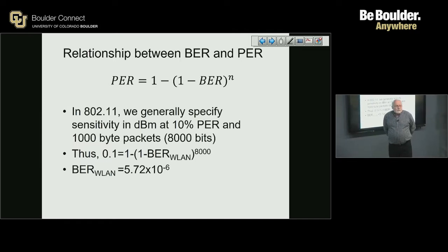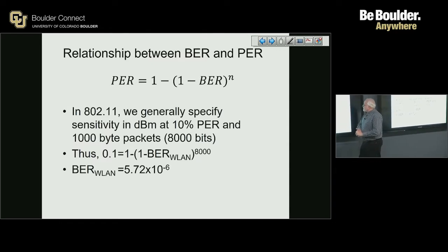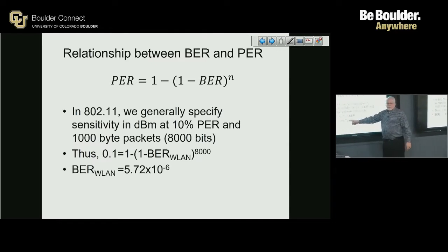If you actually took a tool and measured the throughput, you'd see that a lot of times in Wi-Fi, in a crappy environment, you're doing worse than 10% packet error rates. What happens in Wi-Fi is that we try to do rate adaptation. The access points have algorithms to maintain the packet error rate within reasonable limits. They lower the modulation rate, make the fragment sizes smaller, or do other things to keep the packet error rate within acceptable limits. Like I say, this sounds like a lousy channel, but it's really not that bad.